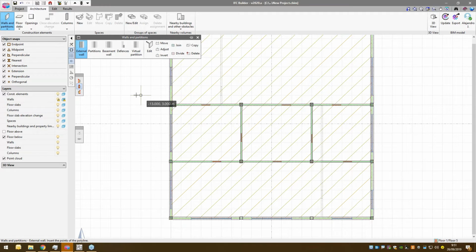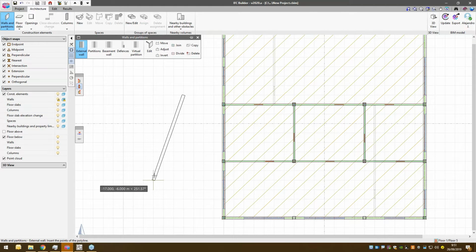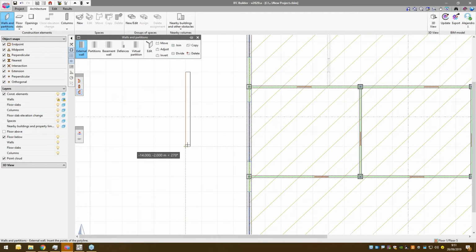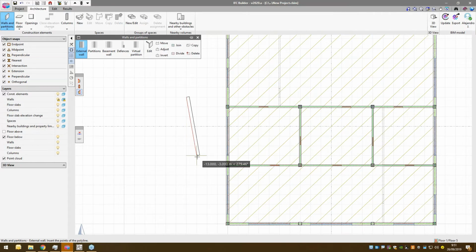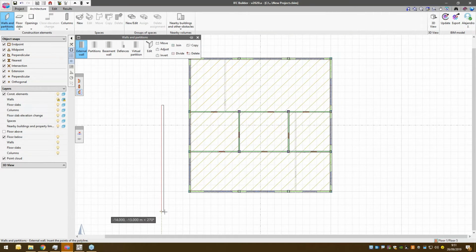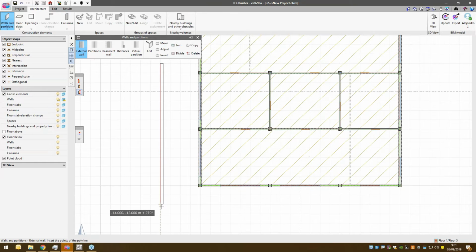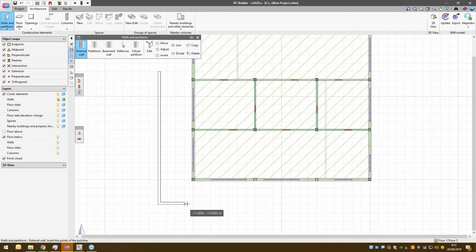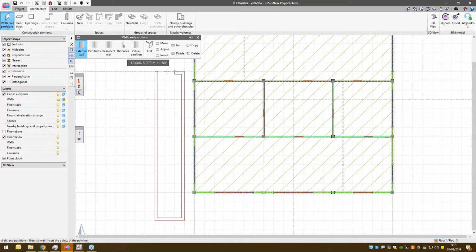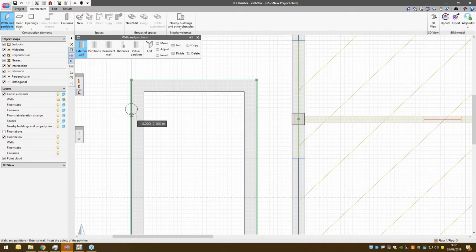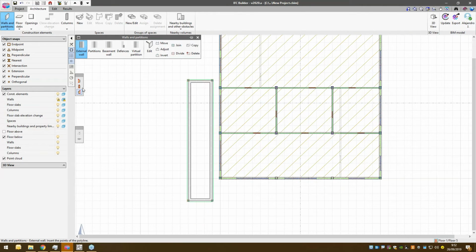What you're drawing is a generative line or a reference line. That means that you can define if it's going to be in the other side or in the inner side, because this program is only for basic drawing, and afterwards we are developing more software in order to define the different layers of the wall. That means that for now you can just draw wherever it's more comfortable for you, and afterwards you're going to be able to decide whether this is going to be a brick wall or stone wall or whatever. For now, you can decide this, okay?